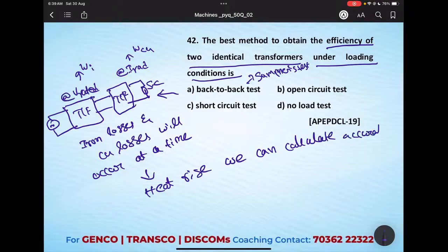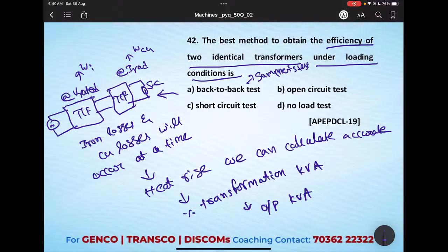What is the need of heat rise? It will affect the percentage of transformation kVA. That means indirectly it will affect the output kVA. So it is going to affect the efficiency.